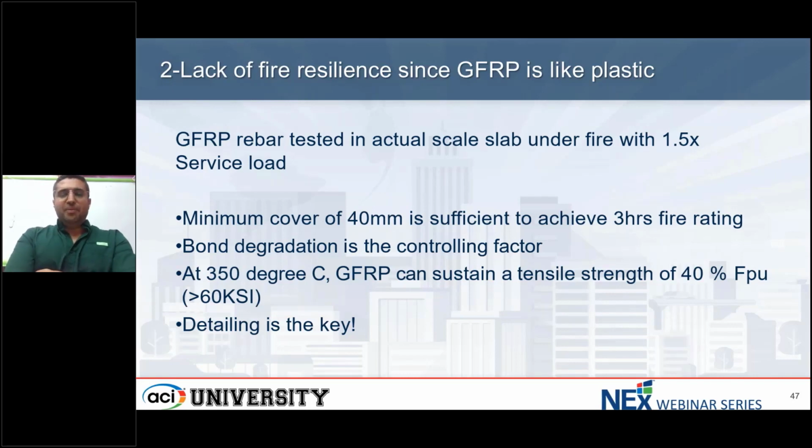And this is very common because people say, Borna, the material is plastic-based. Well, that's true, but before a material is considered plastic, you should consider that 85% of this material is glass. And even in a fire, after 2 hours, when even the polymers start to degrade, the glass is not going anywhere. Glass has a melting point even 300, 400 degrees higher than steel reinforcement. So we won't have any problem.